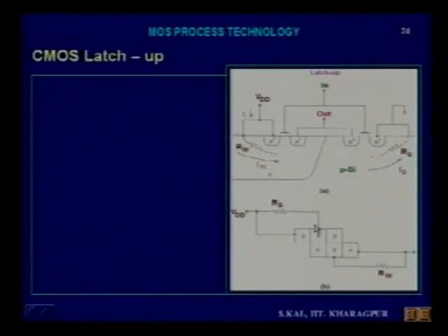So it's already biased. Similarly, if you look into this structure, the P region is common. What is the P? The P silicon substrate. For the PNP transistor, this is the collector, and this is connected to the base of the NPN, and this P will act as a base because N, P, and N is the base. So this is the NPN. That means we found that the collector and base are common in both cases. Either PNP or NPN, the collector and base are connected.